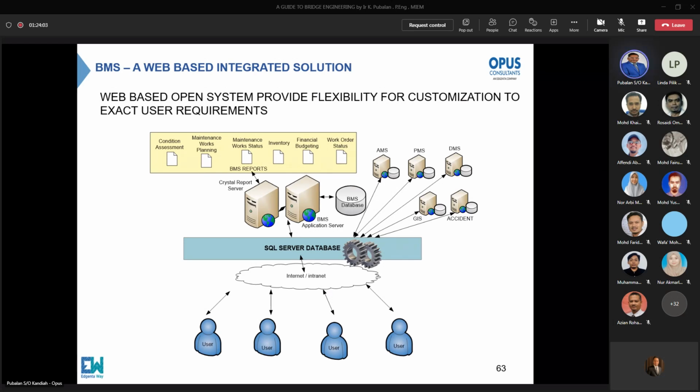There is no problem whether you want to use checker plate, or a precast concrete panel, or some kind of cement board. It's all right. But the most important thing is the friction coefficient. Remember last time when we designed for friction, the formula is F equals mu R. So the value of mu is very important. That plays a role. But generally, when I did temporary bridges before in Sungai Kantan and so on, Mersing, we used checker plate.